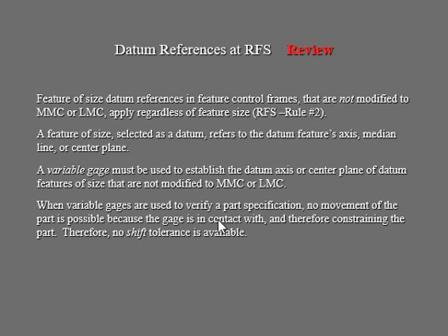To make it easy, every time you want to identify or establish the datum, point, axis or plane, we're going to use the gauge physically, at least as you did in the lab. So when variable gauges are used to verify a part specification, we're going to make sure that your gauge is in contact with your target datum, point, plane or axis. Try to make it as perfect as possible, meaning we don't want a shift of tolerance when we're trying to verify the tolerance. Okay, all right.